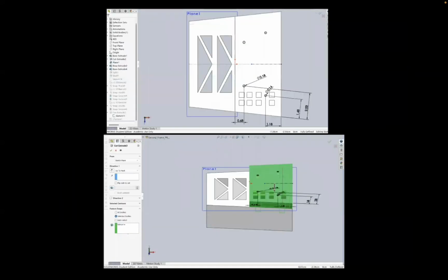After we got the hooks, we make the four screw holes, which will be combined with band holders to make the component stable. The dimensions of the four holes are matched to the real screw diameters, and the position is set to a place where it will not affect the electric cords. We cut extrude the four holes up to the next phase.